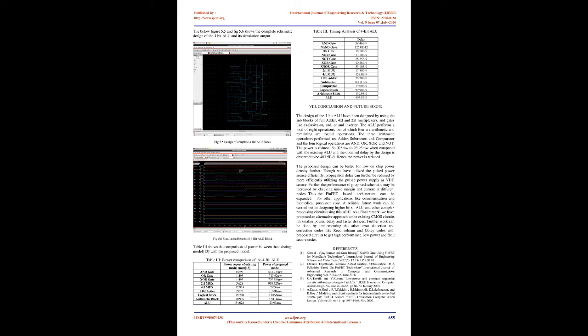The 4:1 multiplexers have 2 select inputs. The muxes are used to provide the proper input signal for the adder circuit depending on the operation being performed, and also to pass the output of the full adder to the 2:1 multiplexer for further selection. The select line S2 is used for the 2:1 mux for selecting the arithmetic function, S2 equals 0, and the logical function, S2 equals 1, as shown in table 2.